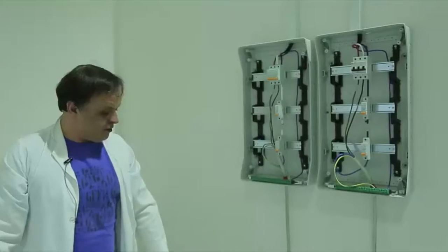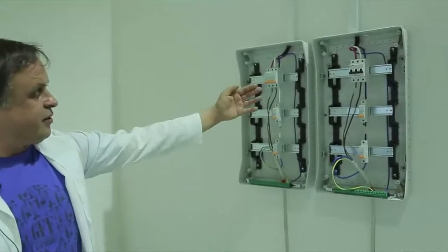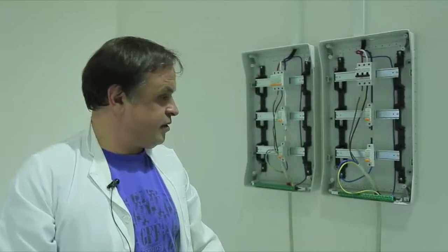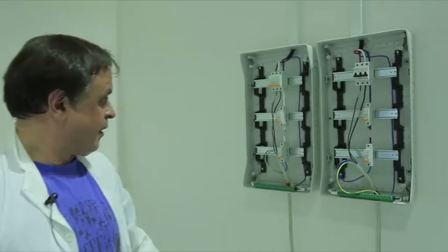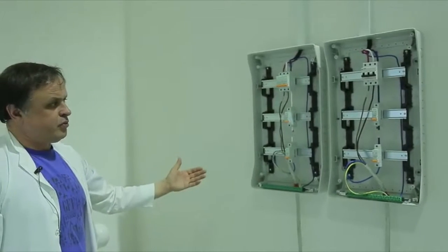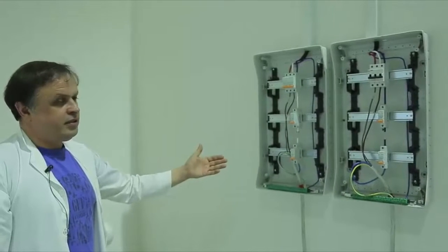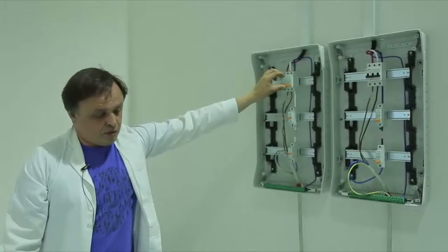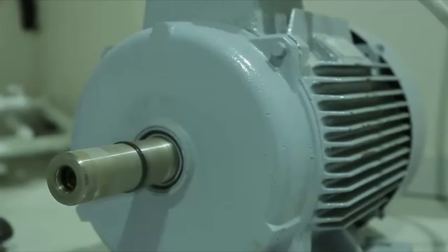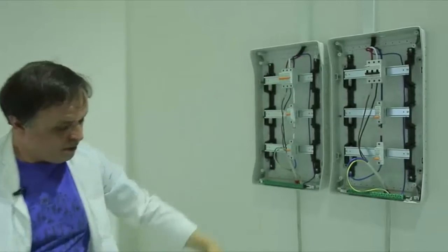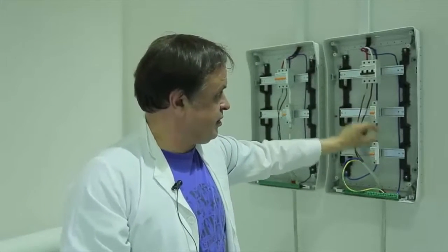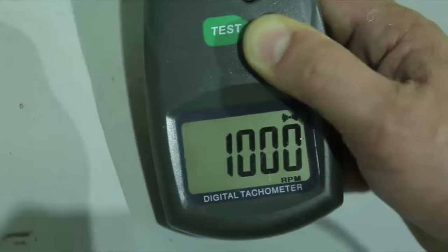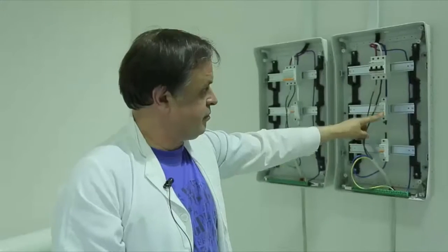Next know-how. For better illustration, let's consider the performance of an asynchronous motor of a new type, motor in the part-phase modes. Connect 3 phases to a standard asynchronous motor and connect 3 phases to an asynchronous motor of new design. Let's demonstrate performance of both motors in the mode when 3 phases are available. The standard asynchronous motor with power of 10 kW is running. The asynchronous motor of new design with power of 7.5 kW is running as well. We use a laser tachometer to monitor the motors' revolutions.